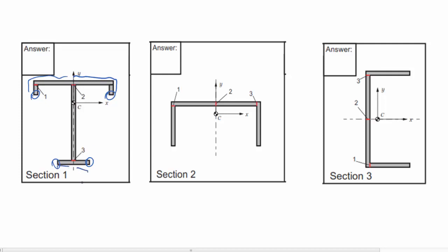This means that the 2 possible locations for the highest shear stress are location 2 and 3. Now we should notice that for point 2, the path from the point where it's 0 to point 2 is a lot bigger than for point 3. This is why point 2 will be the point with the highest shear stress.